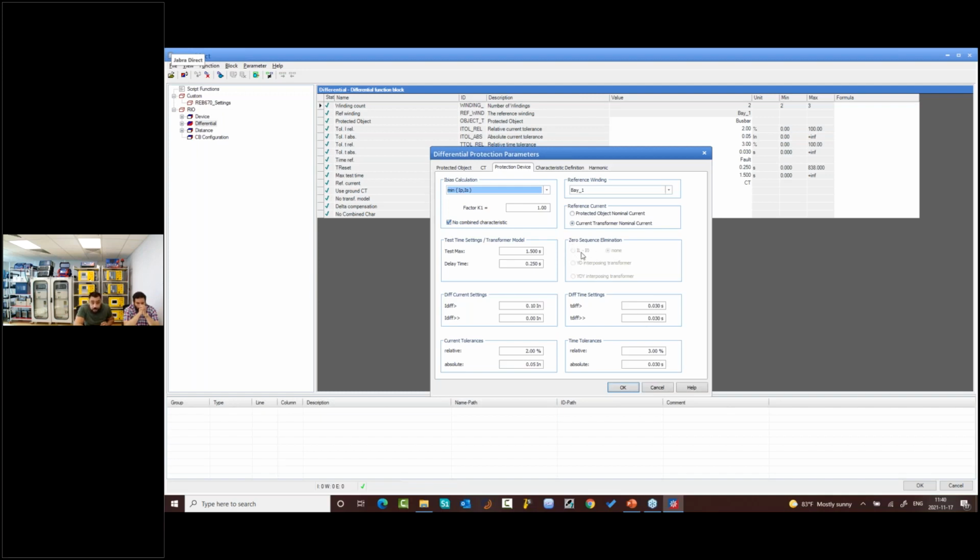This is very important, zero sequence elimination, but it is not related to the busbars. It is related mainly to the transformer. If you have an external elimination for the zero sequence component to avoid mal-operation in case of a single phase fault, or if you have none, so you are eliminating the zero sequence externally using an interposing CT, or you have a dedicated interposing CT and you need your CMC to inject on the interposing CT, then it will eliminate. Then you need to tell the Test Universe what kind of interposing CT. Is it a star delta transformer interposing CT or a star delta star interposing?